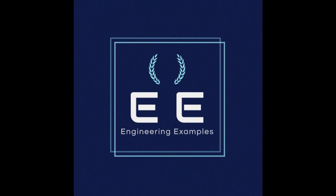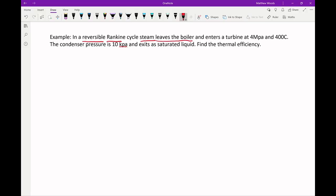Today, we'll be going over an ideal Rankine cycle, also known as a reversible Rankine cycle. So jumping right into it, in a reversible Rankine cycle, steam leaves the boiler and enters the turbine at 4 MPa and 400 degrees Celsius. The condenser pressure is 10 kPa and exits as a saturated liquid.